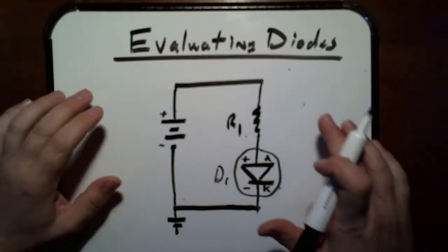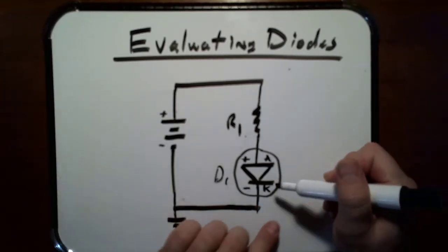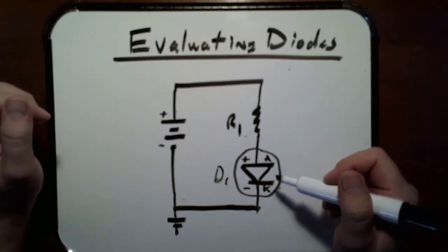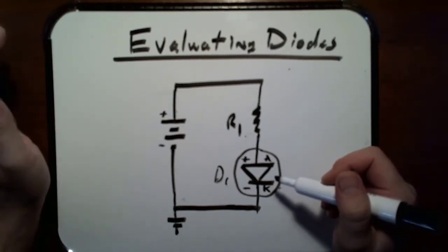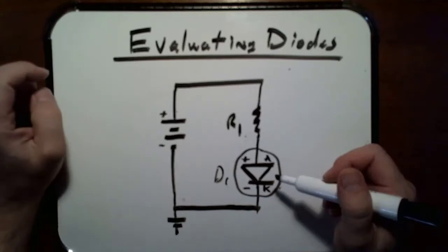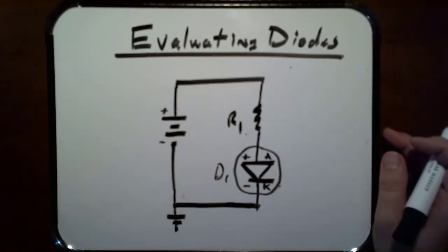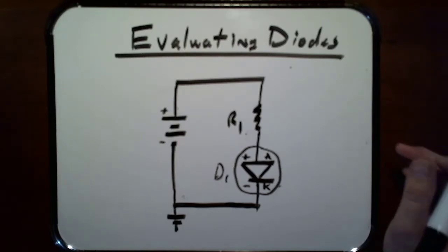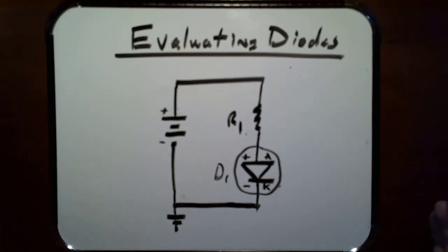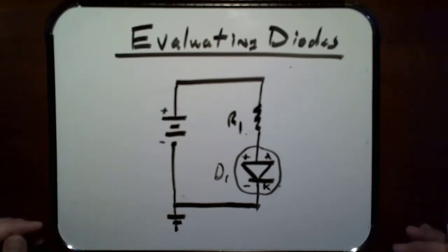We have the same kind of idea in circuitry. We need to figure our solid state components out first. They're greedy, they're going to take their voltage first. And so we need to find out if they're even going to turn on, because as we found out when we were studying ideal diodes, if the diode was conducting, it was treated like a piece of wire with no resistance. We know in reality that's not true. There's a little resistance, it takes a little voltage, and it's taking some current.